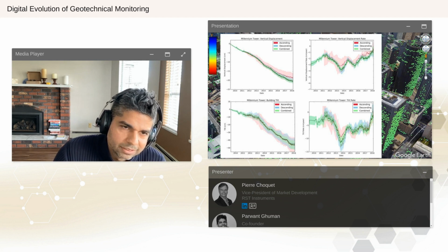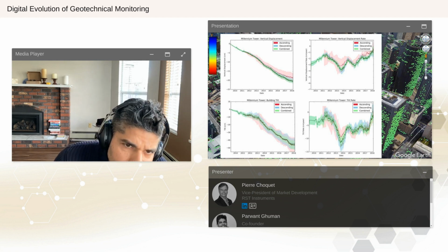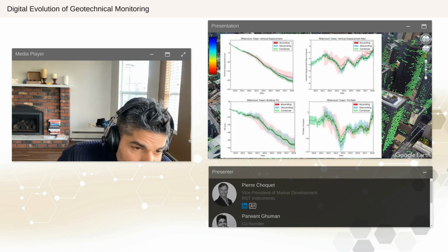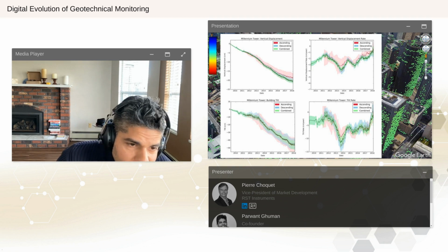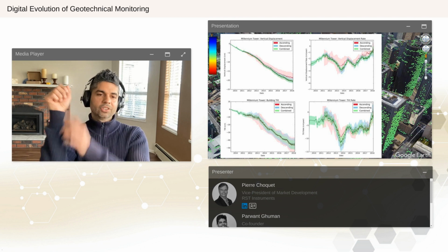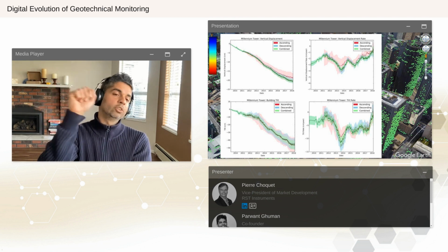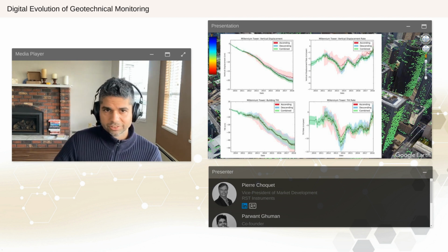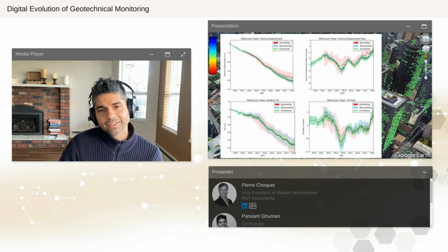So it sunk about 20 centimeters over 9 years or so. And then you also see the tilt on the bottom left. So it tilted about 45 centimeters over these 9 years. So from the base of the building to the top, it tilted towards the southwest, as it turns out, by 45 centimeters. And on the right, you can see the rates of the settlement and the tilt.